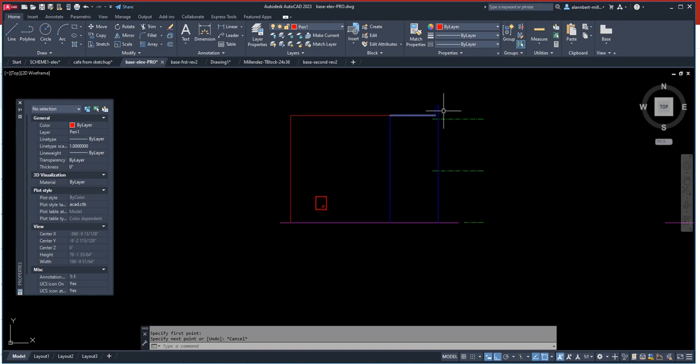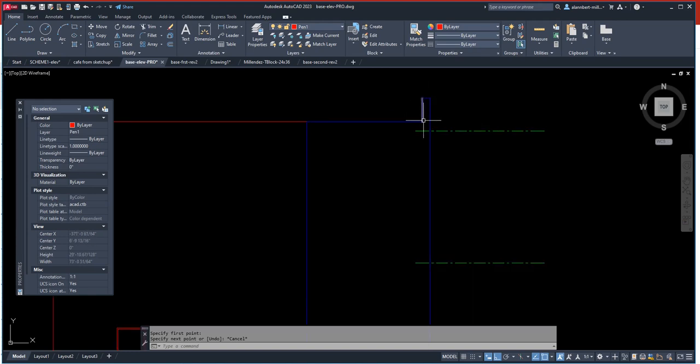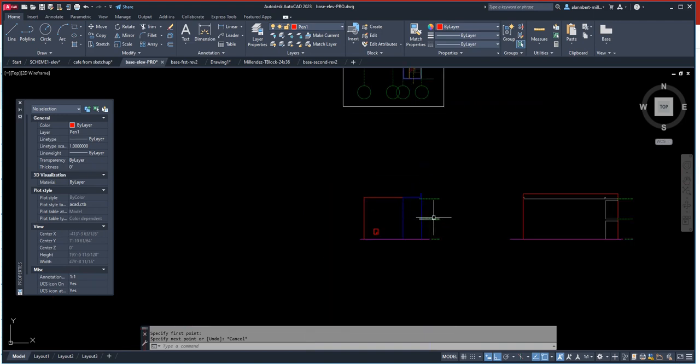This would be the parapet extending. If there was a window here, that parapet will have to extend also on this side of the building. It only extends upwards, but it can also extend this way, especially if there's a window and that window has to be protected from fire that happens on the other property.